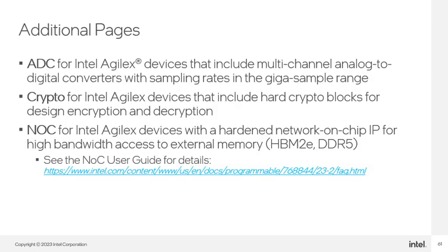3 additional pages are available for supported Intel Agilex devices. An ADC page is available for Intel Agilex devices with A-tile chiplets. The A-tile includes multiple channels of high-speed analog-to-digital converters that can sample in the gigasample range for direct RF applications.